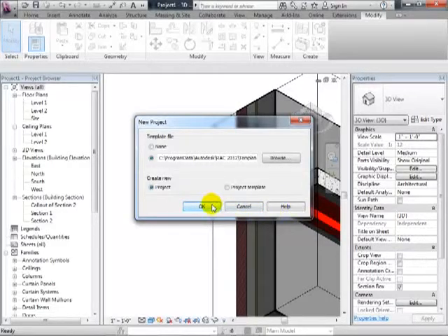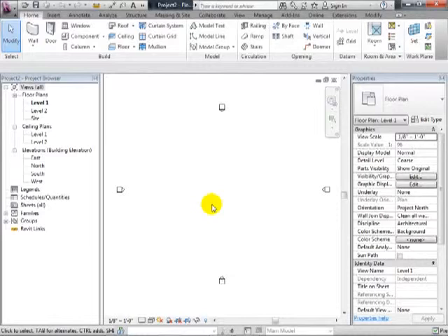So here's one of the little finesse points about working with Revit. If you duplicate things, you won't affect anything that's already been placed because you're going to create a new type. If you change it, you always have to think, have I used that someplace else, and am I going to change something unintentionally? Because something else may be using a type that does have the gypboard in it. So just watch out. That's going to be true of doors and windows and anything where we do some duplicating.